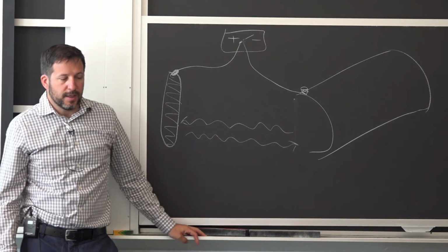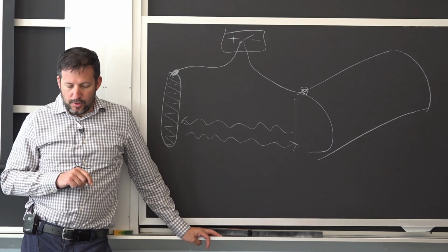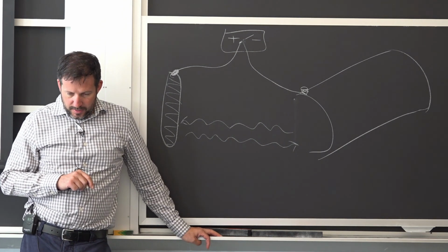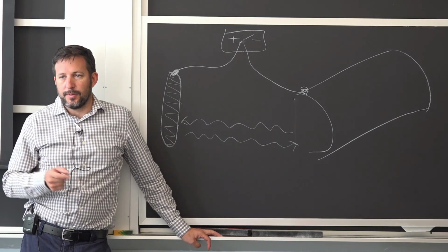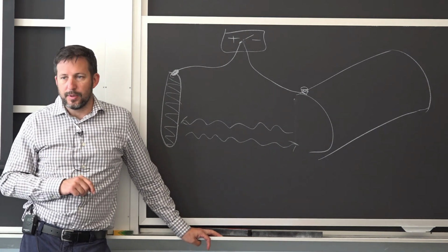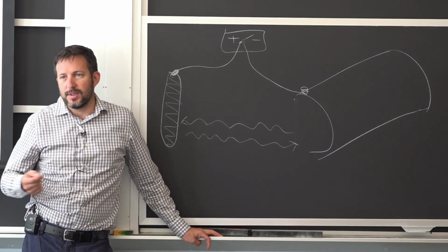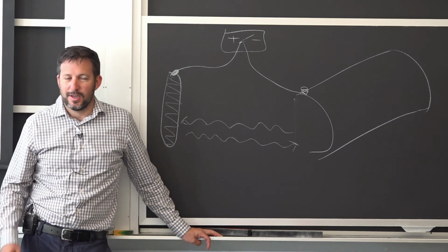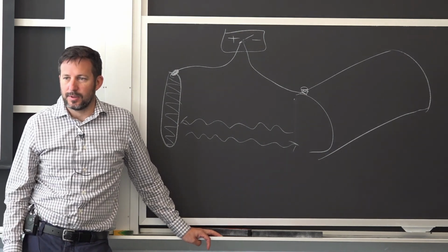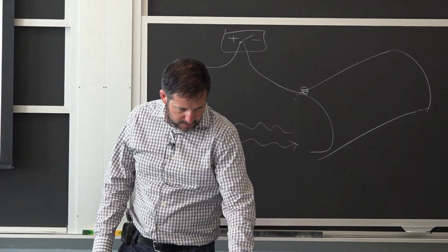Yeah, so in seawater, you made a comment about using the magnesium, and if you look at the outboard motor for little boats, big boats, they do have a magnesium anode that you screw on. So it's a very, very simple way when you're in water. You just tag it along, and it's connected electrically. That's about all we can do.